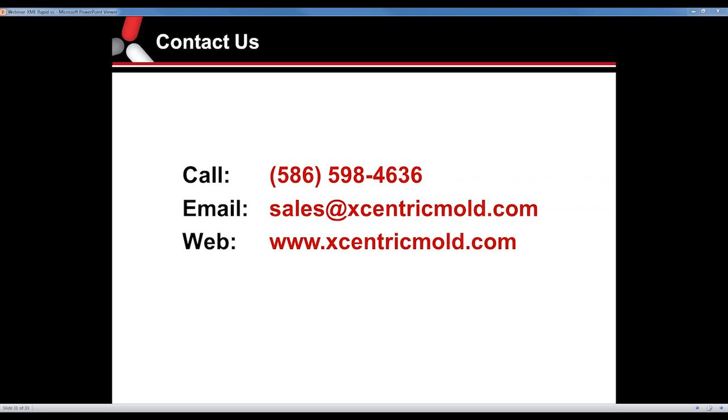Are you able to do high temp resins such as PSU or PPSU? Yes, we can. The mold may have to be built a little bit differently to accommodate heater rods, but yes, we can. And then looks like someone just asked the same question, but for Ultem, yes, we can.